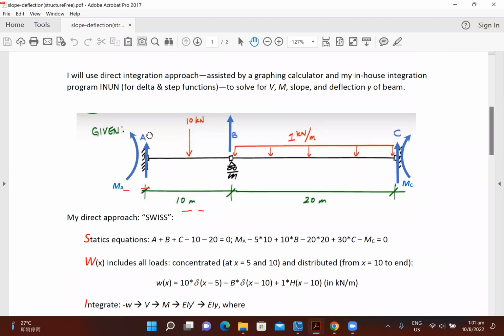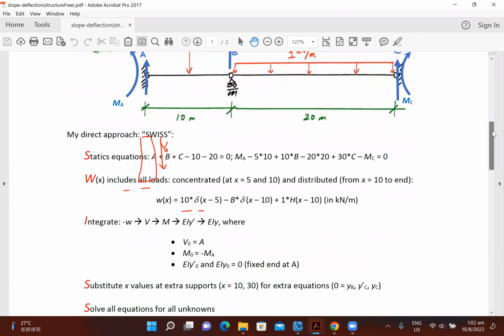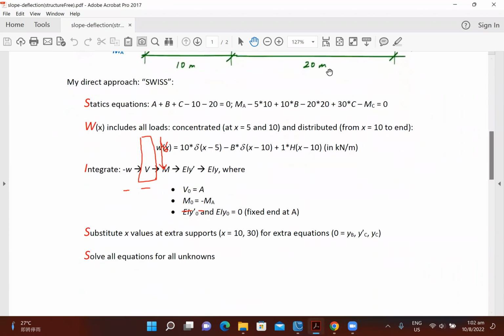So if you consider an infinitesimal piece of beam here, you already have an outward reaction A, and V naught, the starting value of the shear, is whatever is needed to balance that outward force. It is defined as downward positive, so it has to be exactly equal to A, the reaction. All right, so with that in mind, we know the initial value of V being A.